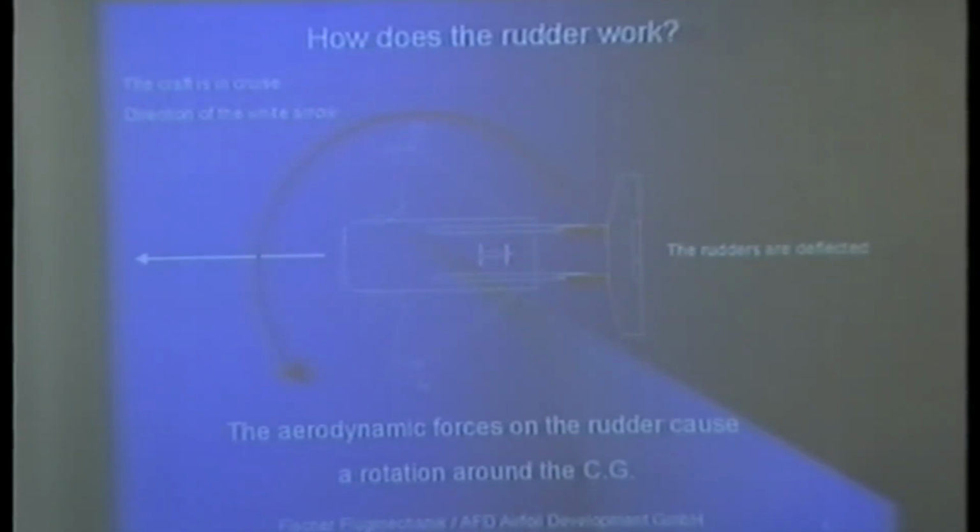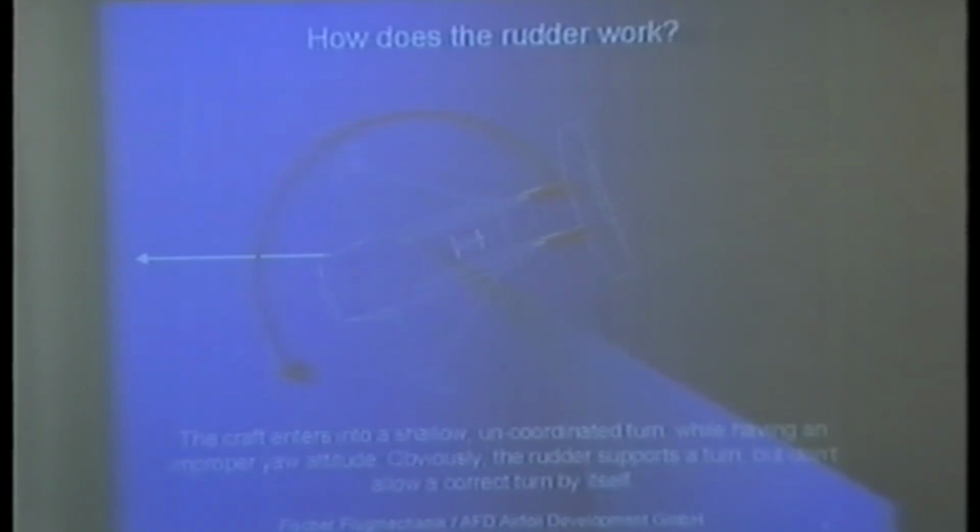You have seen it yesterday, wonderful, in the demonstration with the model. You make this first. This is the turn, but this is a yaw condition. Clear. A yaw condition has problems. You make drag, and when you are in optimum power setting and you come to yaw, you lose speed and you fall down in the water again. To be able to make a turn in yaw conditions, you have to give full power first, and there you need minutes to compensate in advance for the loss of speed during the yaw drag.